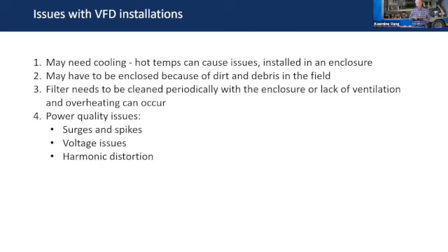You want to close it where your pump station is. You have to clean that filter periodically. And then, of course, we've mentioned power quality issues like surges and spikes and voltage issues and harmonic distortion, where you get that feedback through the line, and it's almost like a wave coming back from the shore that goes back and can blow up a transformer or something like that on a power pole.